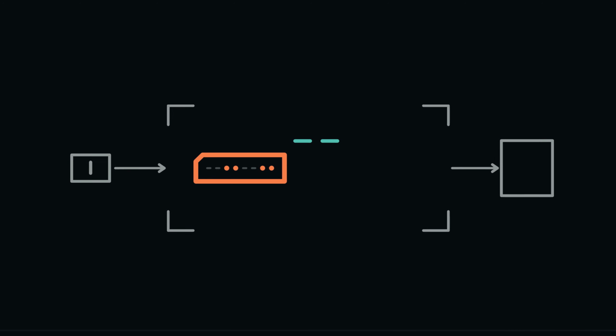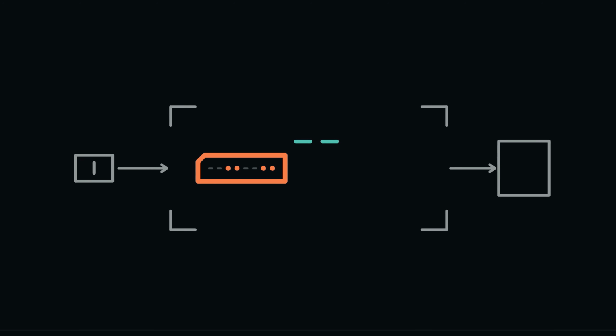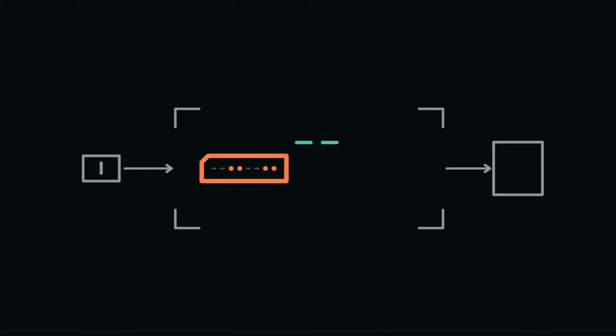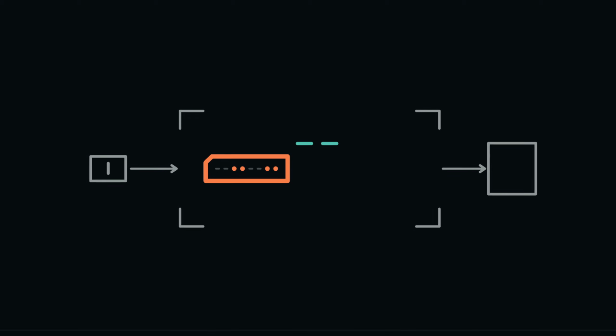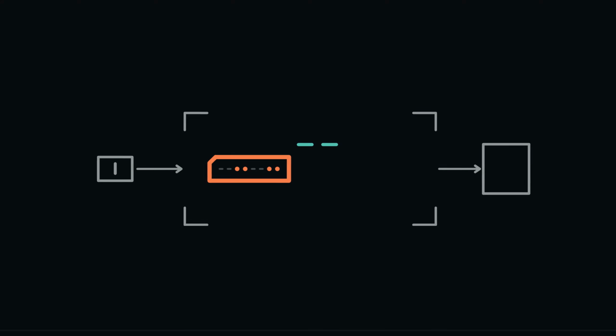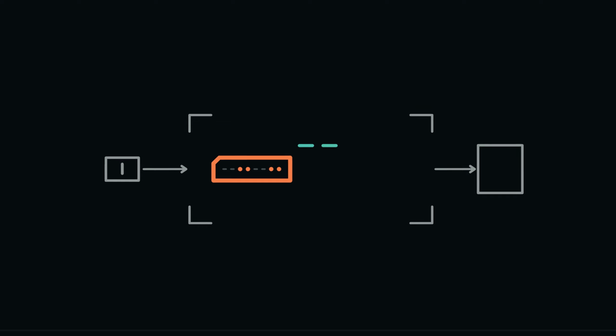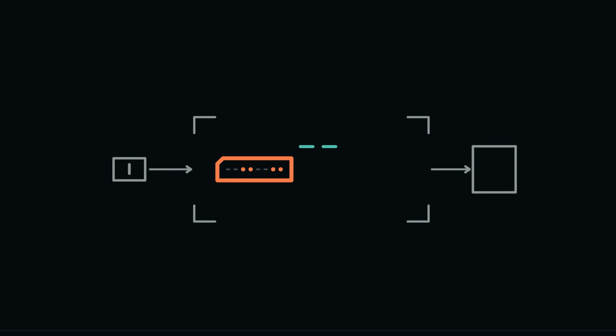Every module built so far settles to an output determined by its current inputs. Change the inputs, and after delay, the old result is gone. But a computer must preserve choices: a partial calculation, the location of the next instruction, the character waiting to be displayed. We will begin with only one remembered bit. The challenge is exact. Establish 0 or 1 with a brief input. Remove that input, and still have the circuit's present state depend on what happened before.